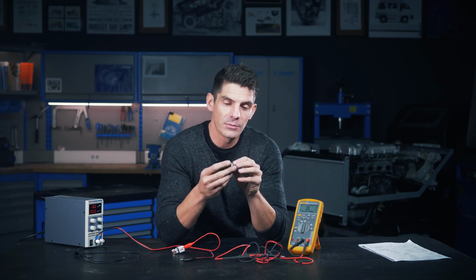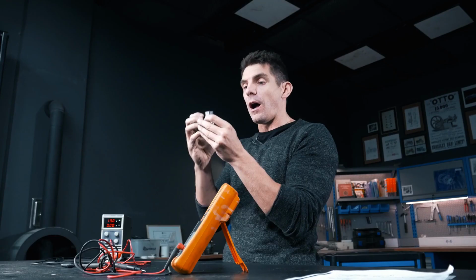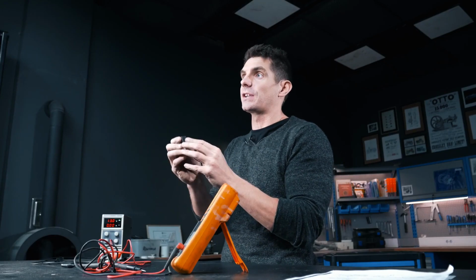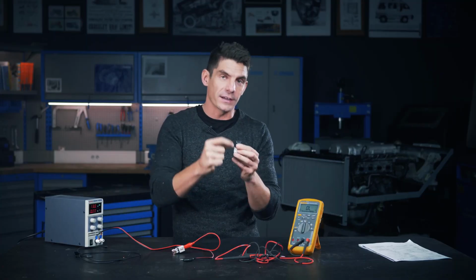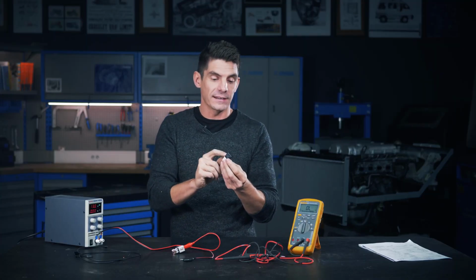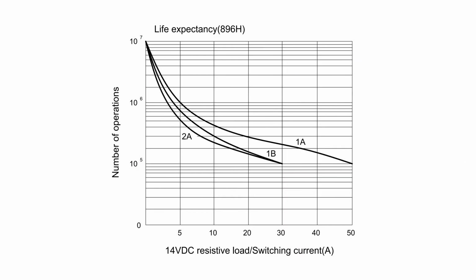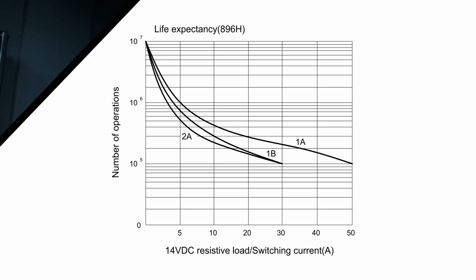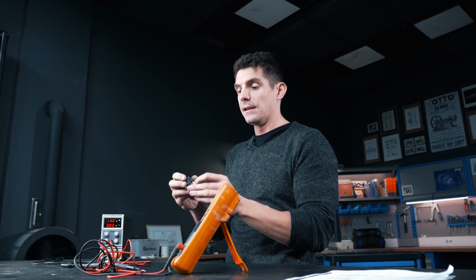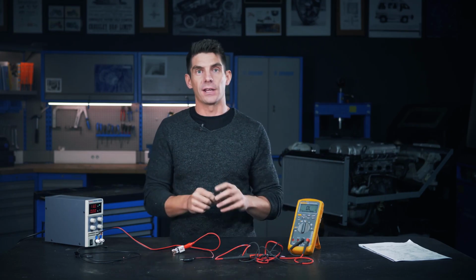Failures. Relays are pretty sturdy, but they do fail occasionally. Every time the relay operates, there's a small arc of electrical current that chips away at the contacts inside here. When the armature closes, there's an arcing between the 2. And you've also seen how delicate the coil wire is inside here. There's a diagram somewhere of a lifespan for a relay that shows that the estimated number of switches that it will make is related to the amount of current going through that relay. So it's interesting that a relay carrying a higher current will fail earlier than a relay carrying a low current.